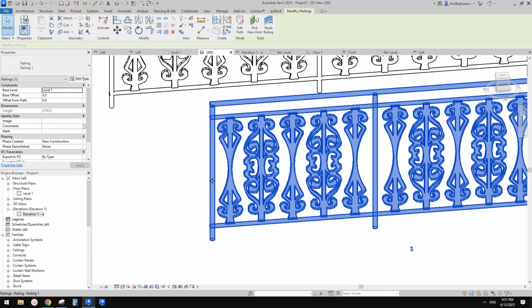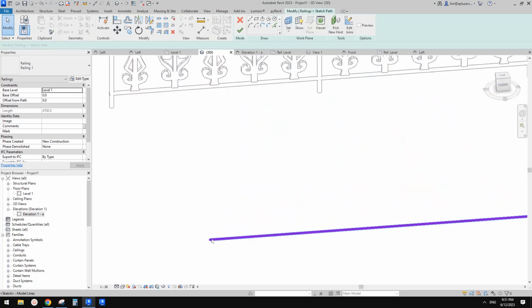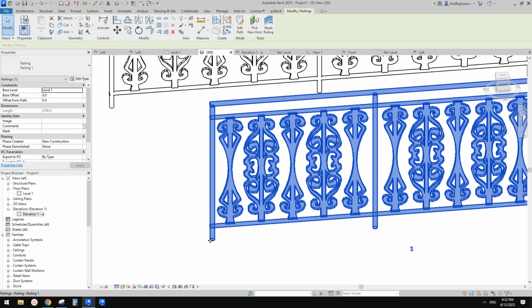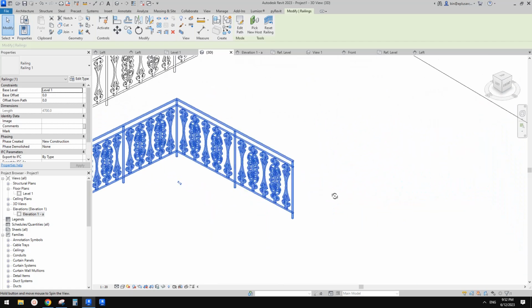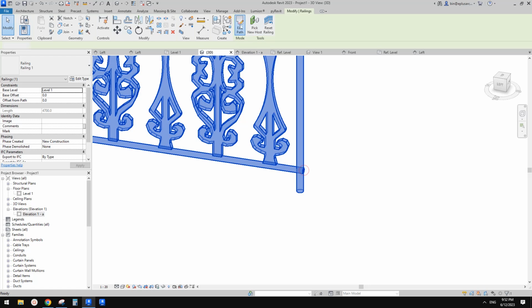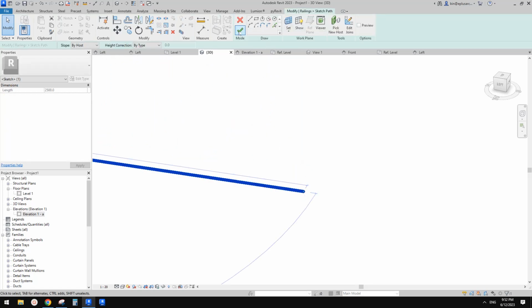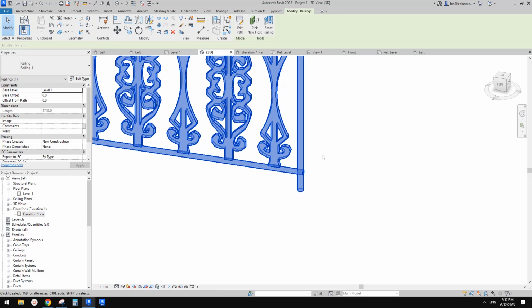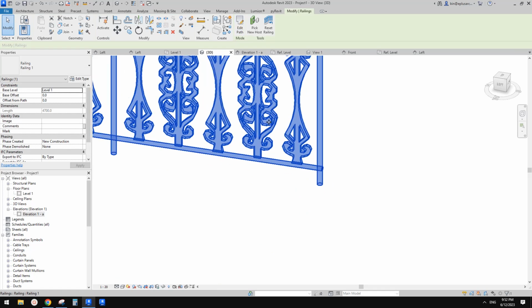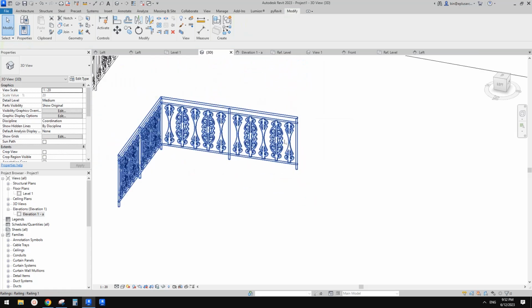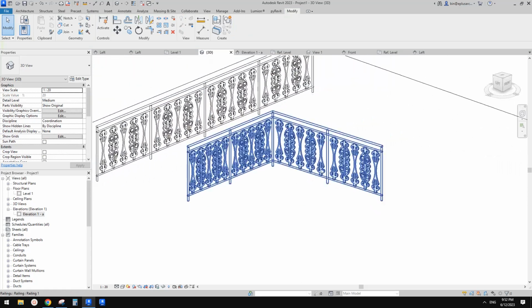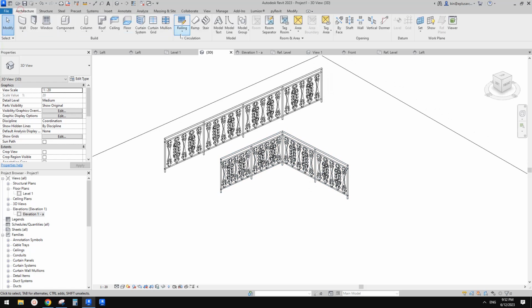Okay, so you can see it will move this one. So it will be within the sketch. It won't always offset by 15. You can see that's the starting point of the sketch line of this railing. Same, if you look at this one, edit. This is exactly where it stops, because we offset this one to the left by 15, by the radius of this railing. And okay, I think this is almost it.